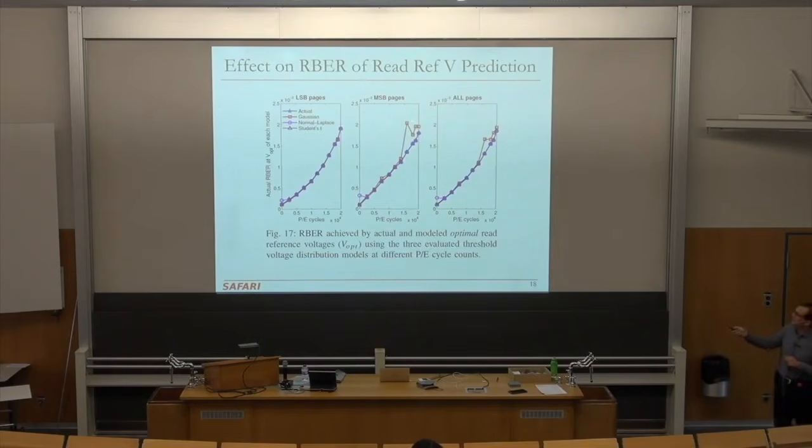So to gain this much reduction in error rate, we do all of that work to model the distributions. But that enables a much longer lifetime, as you can see, right? If your ECC's correction capability is over here, for example, you would reach that correction capability much later in lifetime if you're doing the distribution modeling in a much more accurate way.